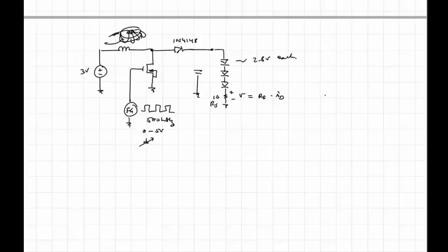So remember that current that looks like this? You'd actually be able to see that here if you take that capacitor off temporarily. So you'll hear more about that. But that's the basic lab that you're going to run. You will light up 3 white LEDs in series using a 3-volt source by building the simple boost converter.